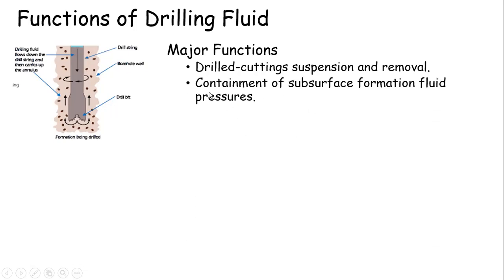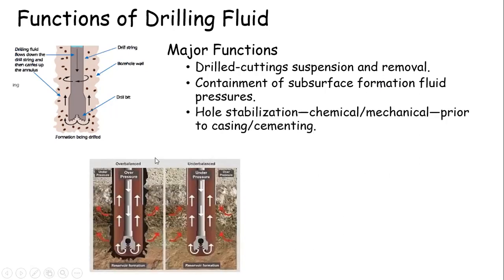Then we also have containment of subsurface formation fluid pressures. There are pressures from the formation which are trying to invade your wellbore, and you need to prepare your drilling fluid to balance that pressure, to exert a certain level of pressure on the formation so that formation fluid does not invade your wellbore.